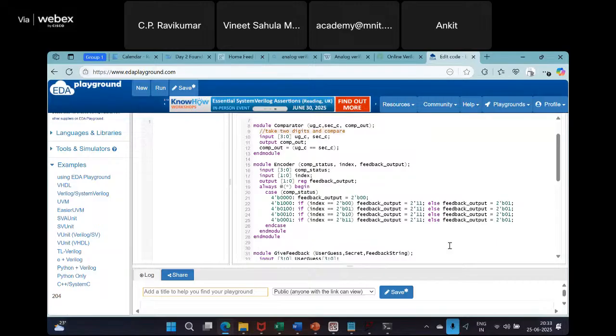See, we sort of know that nothing else will happen. I think there is a default also, right? There is a default that you can write. But this will not occur. It should not occur. So if it occurs, we'll put this 0, but that is a dangerous thing. It should not occur. If it does, something is wrong with our code. But the advantage of giving that default is that then it generates combinational logic. It knows that we have handled all the cases.